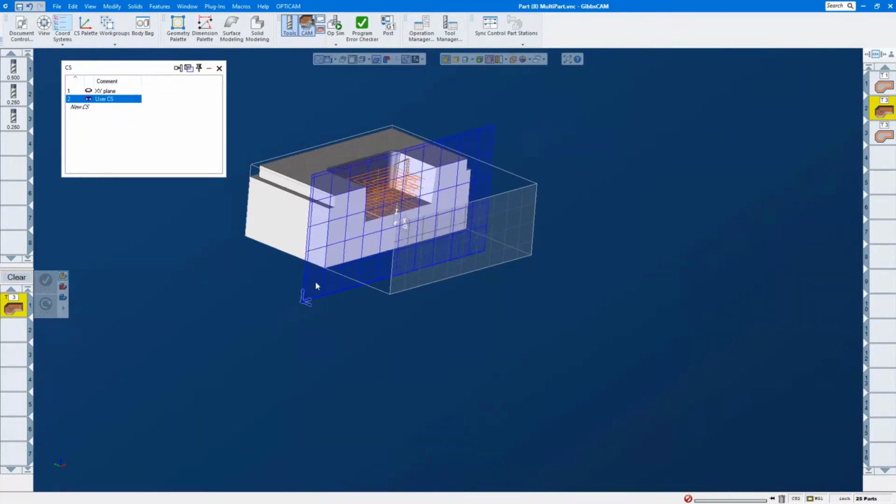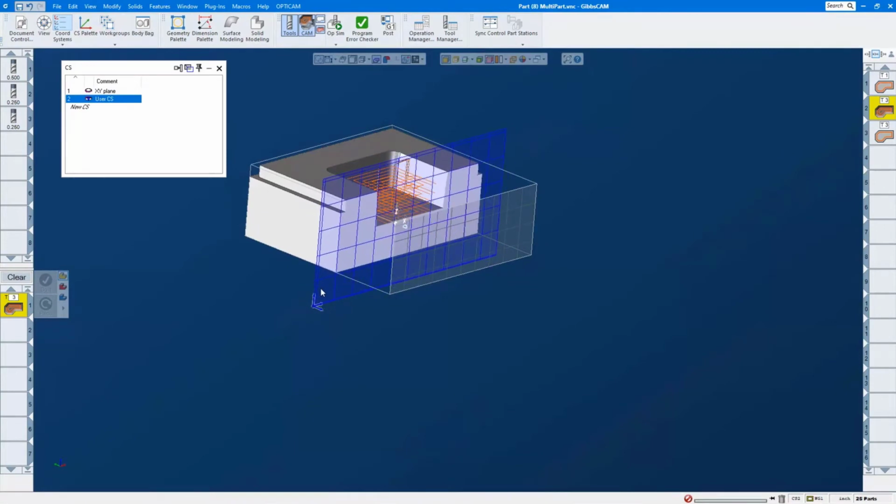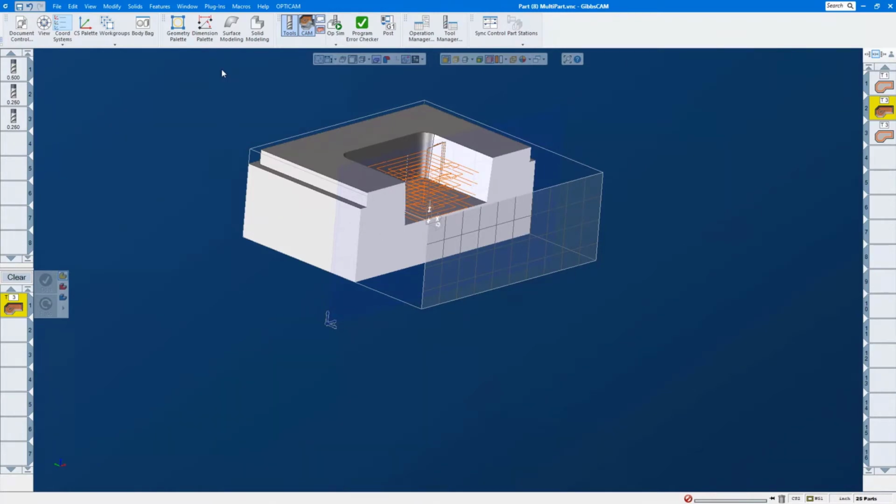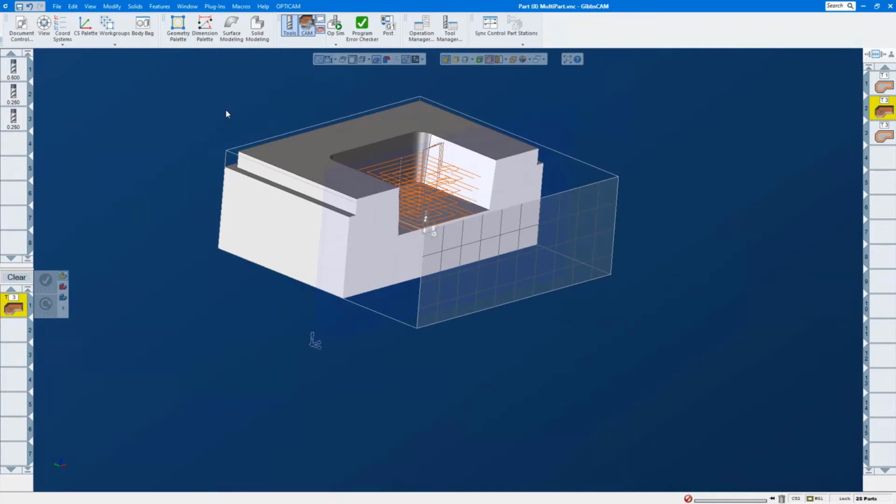That's actually very cool. Again, it's a more complex toolpath, and especially for some of you guys that are doing 5-axis, this could be pretty sweet. It can be pretty helpful for volume L2, where the slices aren't all identical, so you can look through kind of one slice at a time what it's doing. Okay, we beat that to death.